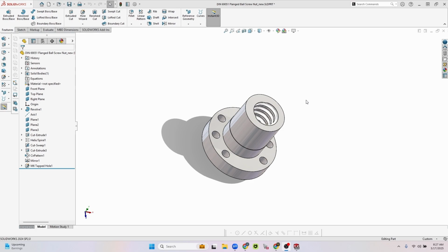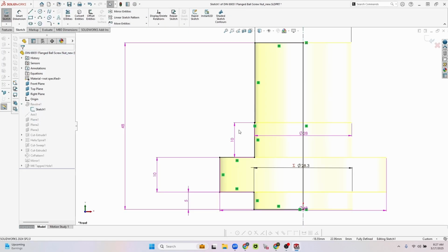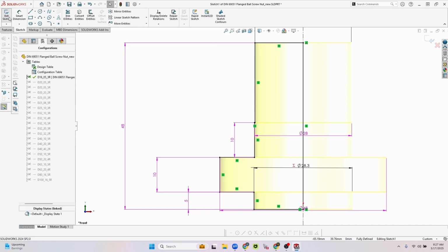The cool part about using SolidWorks for modeling a family of parts is that you can build one model and use the sketch values and the dimension values in building the model, whether it be the extrusions, cuts, or sketches. They can be controlled by these values, and those values can be controlled from a family of parts table.